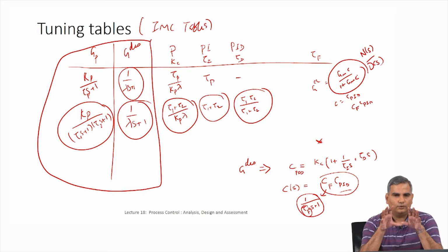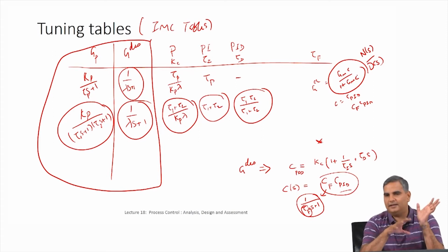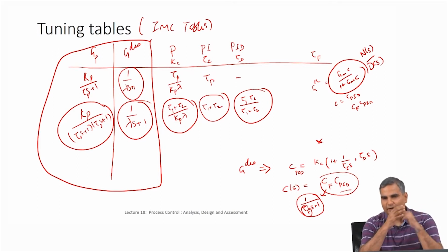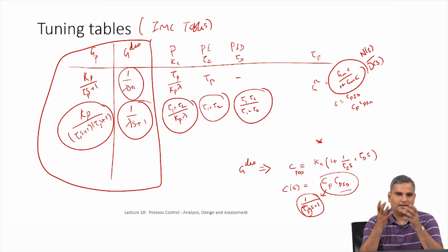and then I showed you in an open loop the inputs are U(s) and D(s) and y is the output. But once you close the loop, U(s) is not an input anymore because it is going to be manipulated, and the values for that are going to be decided by the controller. But the controller is really in some sense driven by the set point that we give. So the inputs in the open loop, which are U(s) and D(s), now get transformed into Y set point(s) and D(s). And then in the open loop we have a transfer function between Y(s) and U(s), Y(s) and D(s), and then you can add them to get the overall effect on y because of the linearity property.